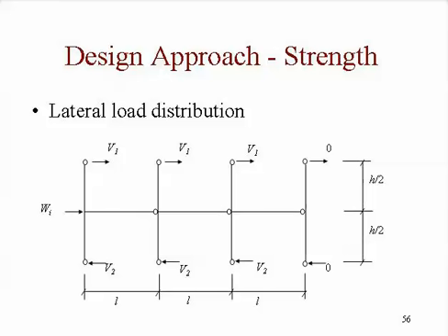So instead of taking the typical portal method, which would divide the lateral load into one part, two parts, and one part, we simply divide the lateral load into equal parts, ignoring the leeward column.